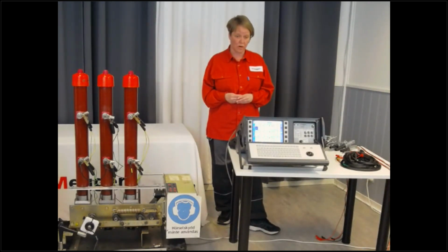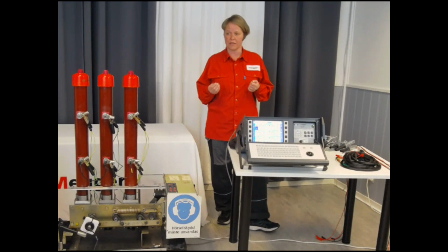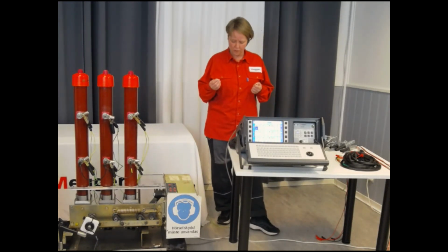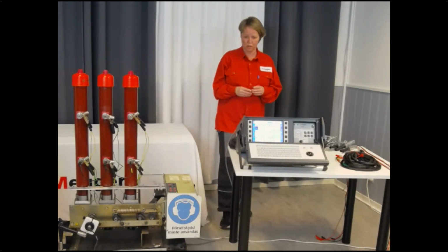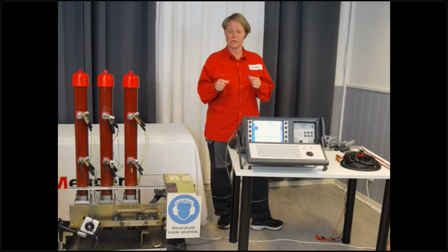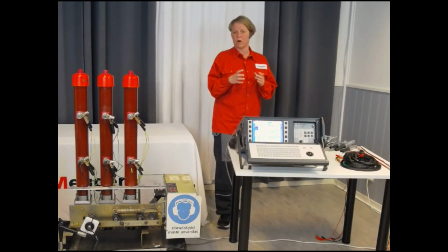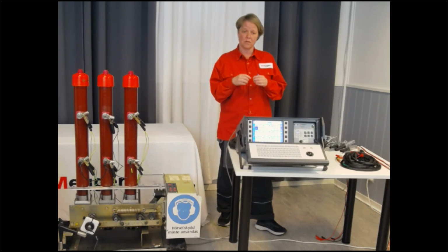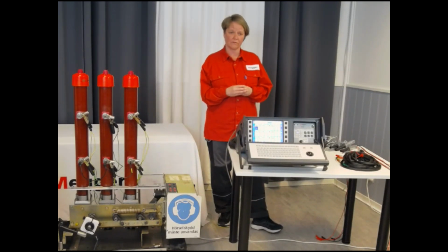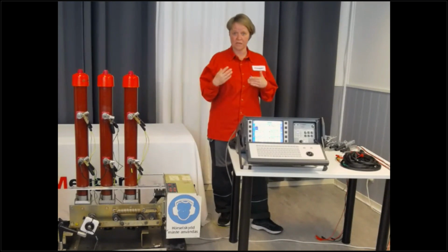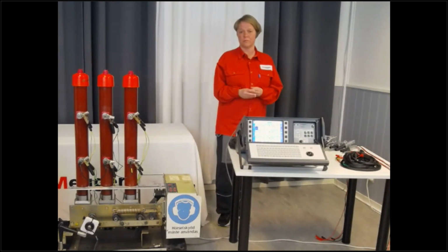So you have a normal timing trace, and if you have trouble getting it to tune, you have to look for any extra groundings. What do I mean by extra groundings? Again, ABB as an example, but we've seen this on other types as well. In that housing where the grounding is, they have a heater, and that heater is on a plate. Commonly that one is short-circuiting the ground between this star and the common point. So you have to make sure you don't have a connection with this plate. This kind of issue can occur. It's not very common, but it exists.